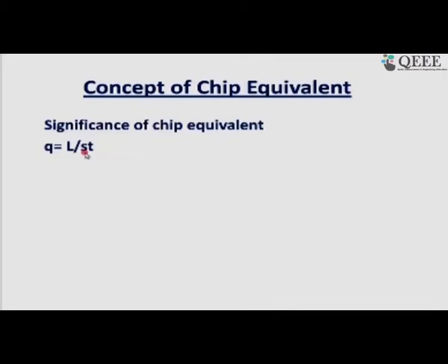So, in that proportion you have to increase the value of L without changing the depth of cut, just by changing the value of phi and phi 1 or the nose radius, and if you judiciously choose that, then this ratio, what is known as chip equivalent, you can keep the cutting temperature constant and without any change in wear on the tool.